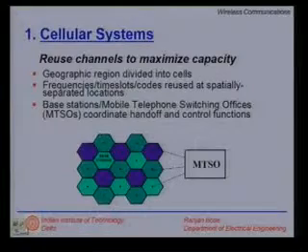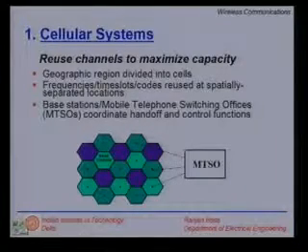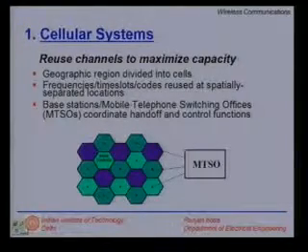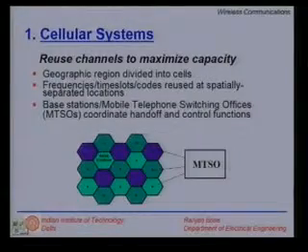What determines the cell boundaries? Well, a couple of things. The first thing is the link budget. Link budget is defined as the total power that is emitted and the total power that is received. So, if we have buildings or foliage or tall towers in the middle which block the radiation, the received power will be less. Consequently, the cell boundary might get affected.